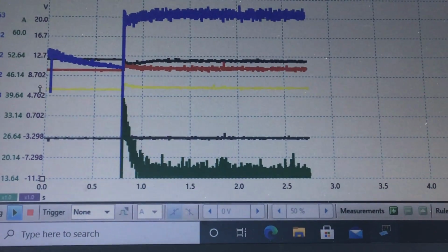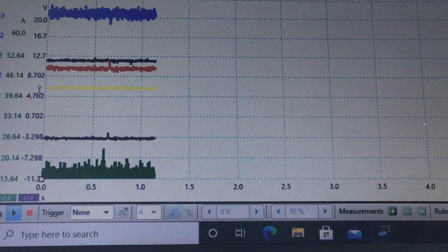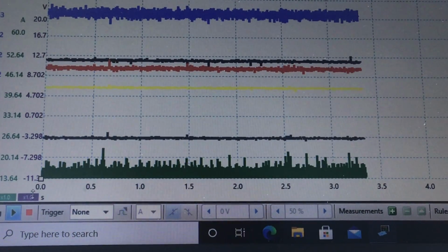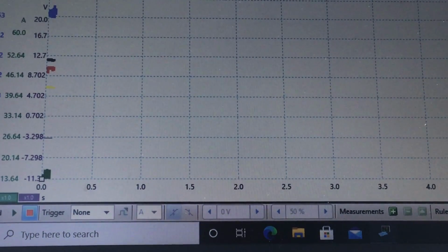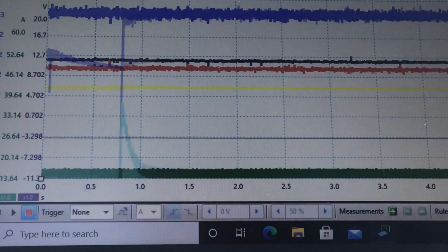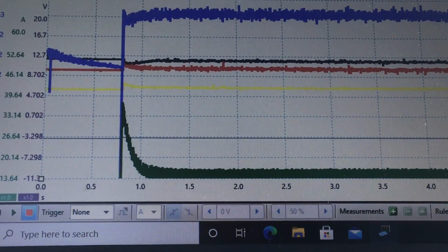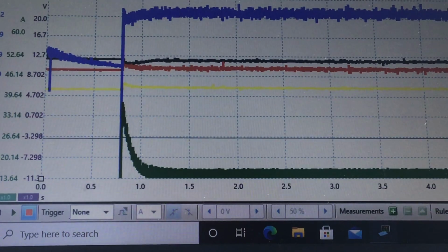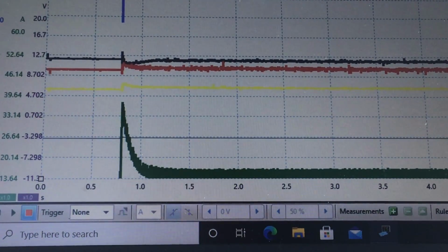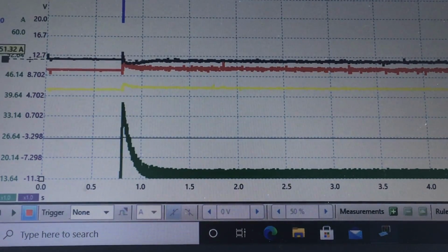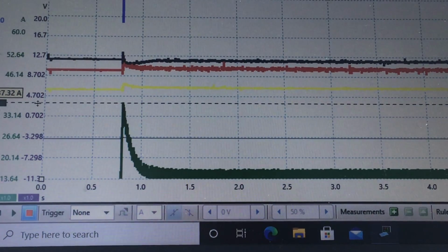Okay, you probably saw something. What I did was remove the blower relay just for a second and put it back. Now we've got something. That's a spike, and that's what I want to take a look at, because it tells us something about how much the rush-in current is. That's the current to get the motor moving from a stationary state.